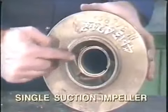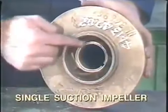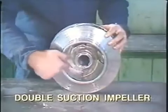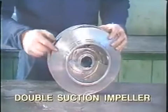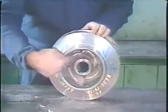Impellers are first classified by inlet design, either single suction or double suction. In a single suction impeller, liquid enters the suction eye on only one side. For the double suction impeller, the liquid is allowed to enter on both sides. It's really like two single suction impellers placed back to back.